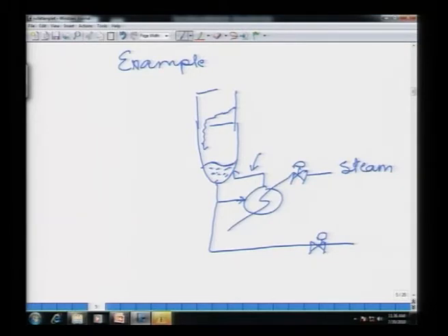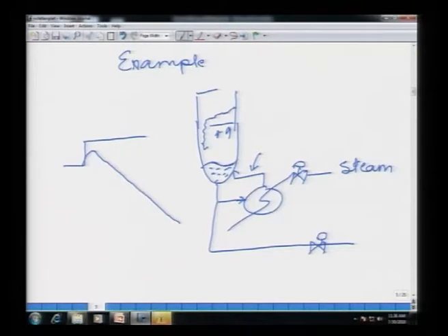What you would find is that actually what happens is, if you increase the steam flow, the level actually first increases and then decreases. It shows actually an inverse response. All right. Why is this happening? It is happening because the vapor that is going into the trays above actually pushes more of the liquid down. Okay. So, the level rises in the bottom sump.